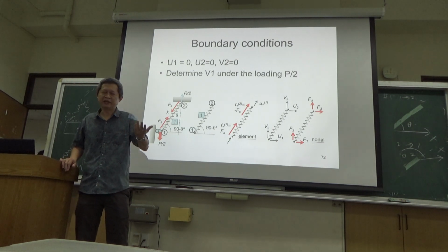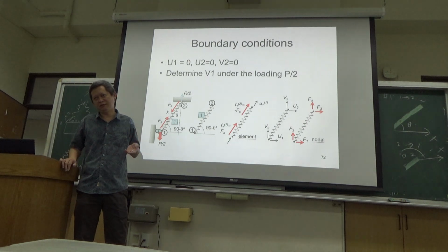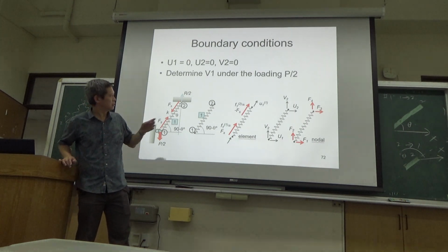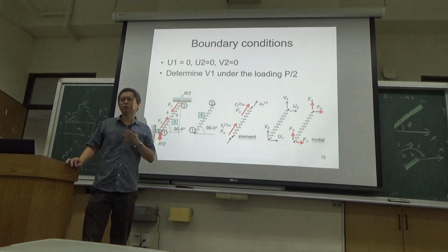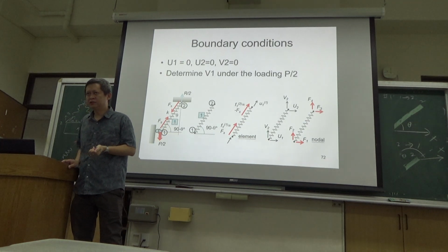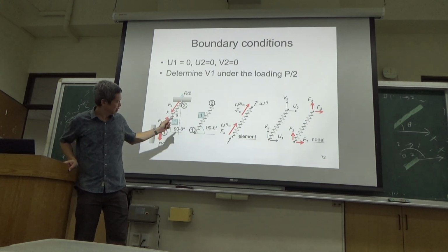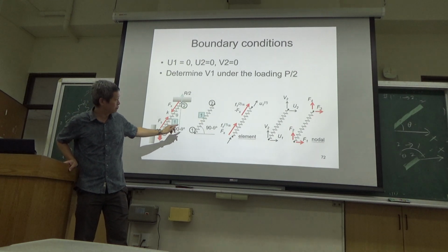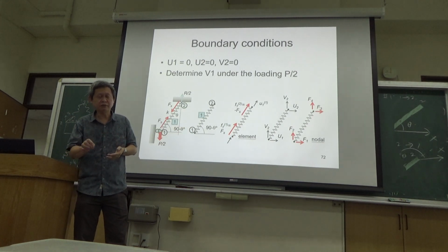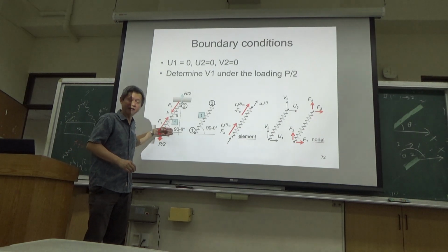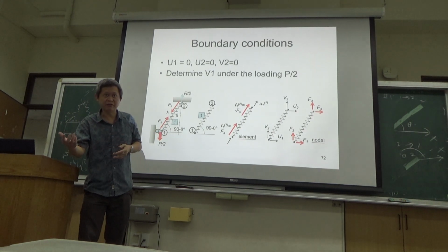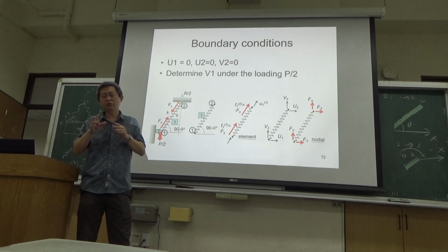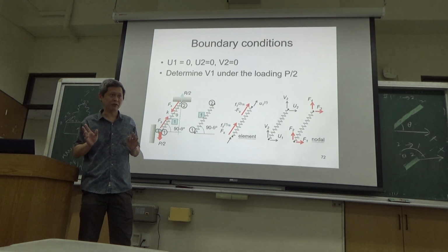It's not more than any arbitrary cartoon. If you're going to use it for engineering purposes, please do your due diligence in checking. Why, even for the first element we did, we have to do this process: hand calculation first, and then the finite element analysis. Does it match with the true calculation? This has been quality control for most of the finite element software.